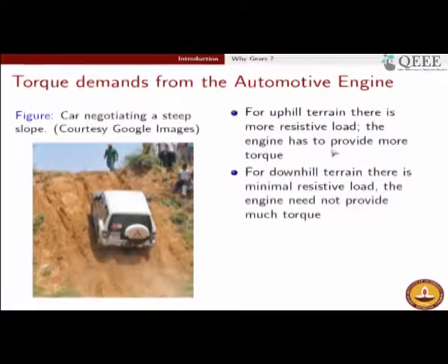But in some other cases there may be a downhill terrain or there may be a flat terrain, in which case the load requirement is not so high. In comparison to this situation, as you see in this picture, if you contemplate the situation when this very same vehicle with the very same driver is driving on a plain terrain, the requirement of the driving torque is not so very high, because the load torque is much lesser as compared to the uphill terrain. So, the moral of the story is, while driving a vehicle, the requirements of torque that has to be supplied is going to be different depending upon the terrains which the vehicle is undergoing.